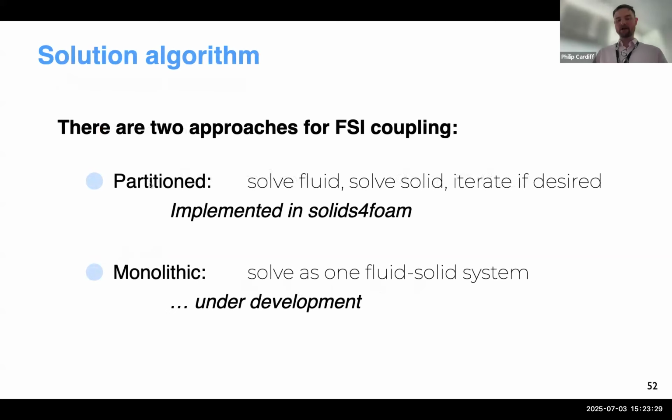The coupling approach is like preCICE, or this multi-region foam. It has a partitioned approach. You solve the fluid, then pass the forces to the solid, and then you solve the solid, and it moves. Then you take the motion of the solid and pass it back to the fluid domain, update the fluid domain, and then you maybe iterate within a time step. So that's the main approach in solids4foam.